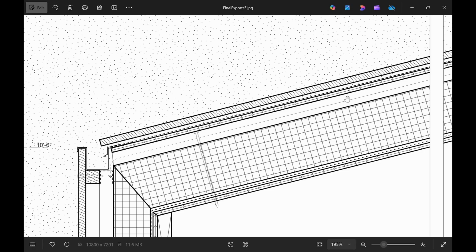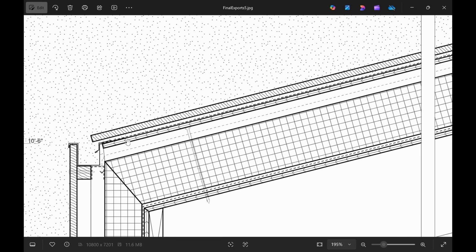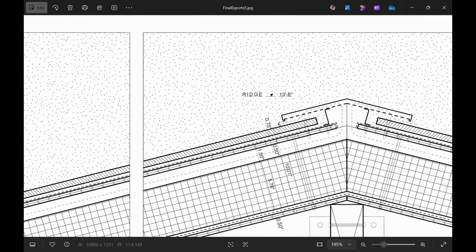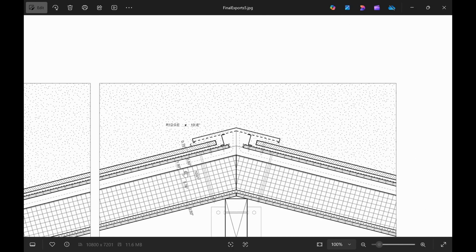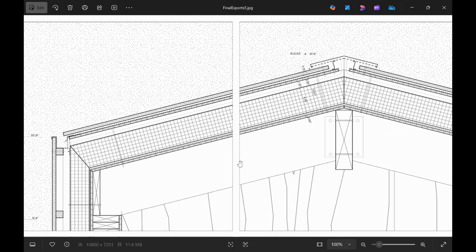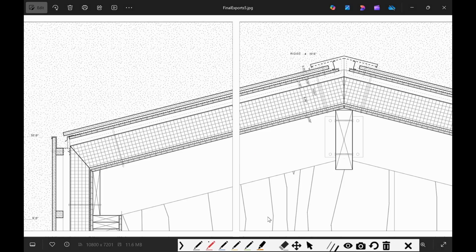and then you're going to slowly get water damage over time. So what people typically do is they'll circulate air through here, and then you'll have this perforated ridge vent that will come out, and the air will actually come through there. So it's always circulating, so it always keeps it cold. So in reality, if it was the winter time, you would see a lot of snow packed up on here. Actually, there would be snow that's just packed up on here because you want to keep it cold.